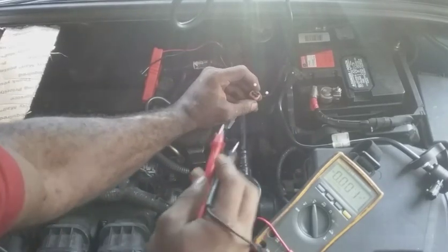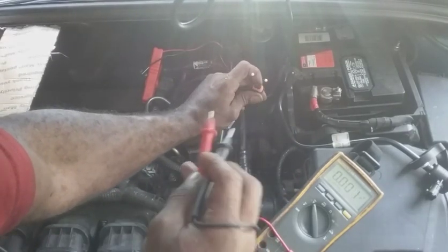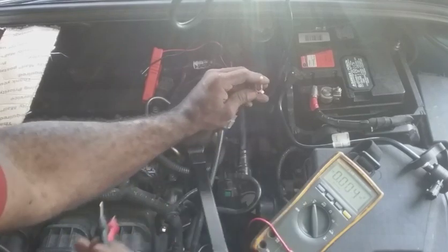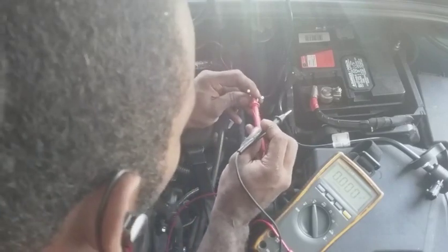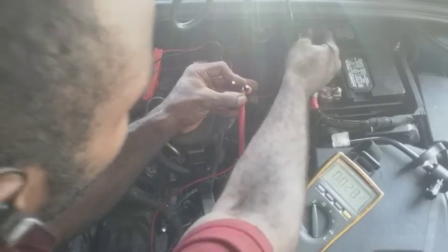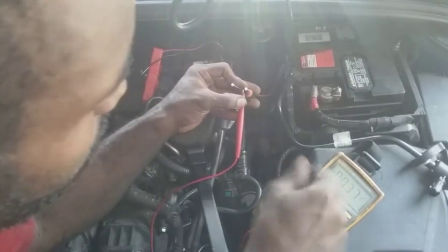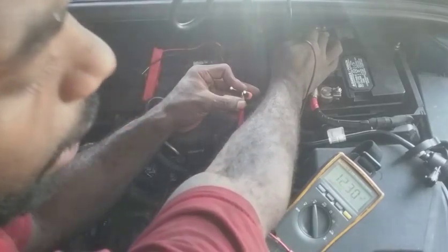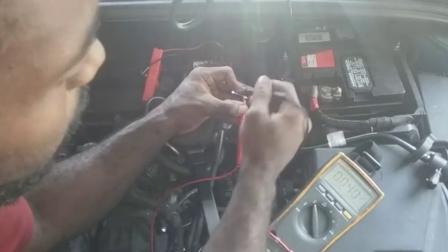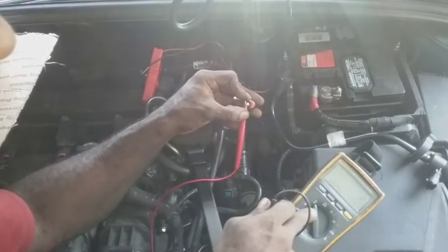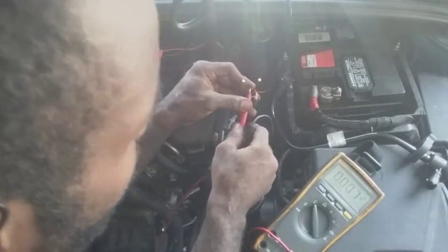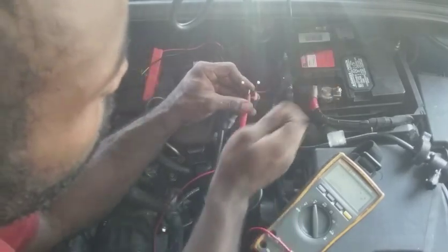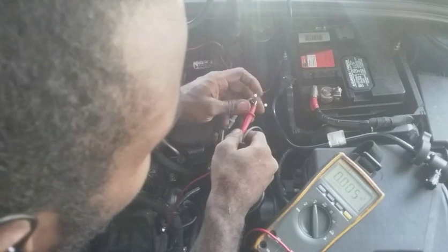it's going to be low because that switching circuit has a resistance value. Normally they're about 2K ohms. Let me find a switching circuit and ground that out with the body. Well, that's good because you see now we got 12 volts. So this is technically the 12 volt side. So I'm on voltage still, and on the green and white wire, this is the constant 12 volts with key on, engine off. Now this should be my switching circuit, the one that has the high resistance.